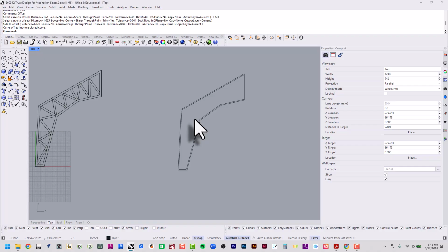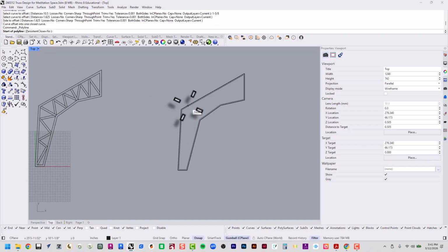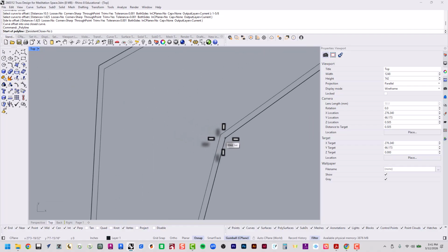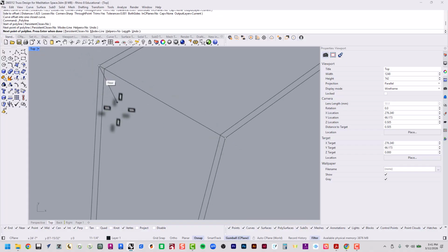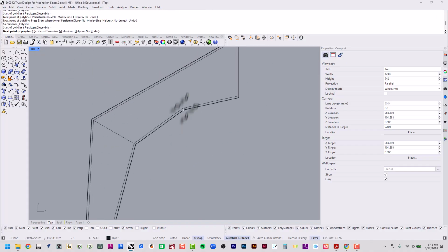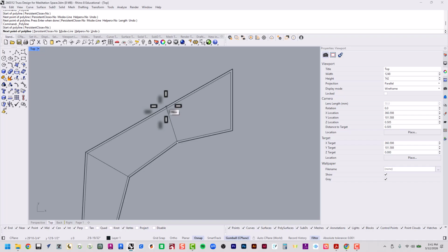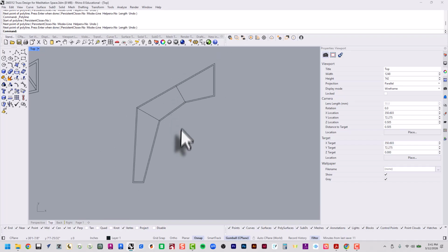Let's draw a line from here to here, right at that crack. And then from here, I guess, maybe we'll go perpendicular like this. Make sure you have the right object snaps on. I already have end, near, point, mid, center, intersection, perpendicular. O snap is enabled. Okay.